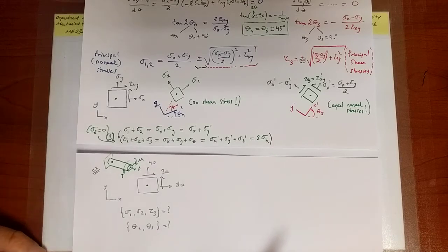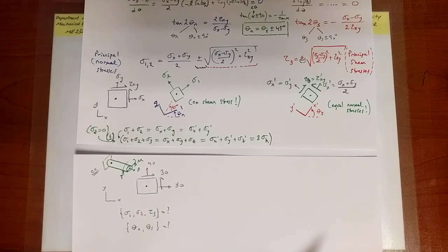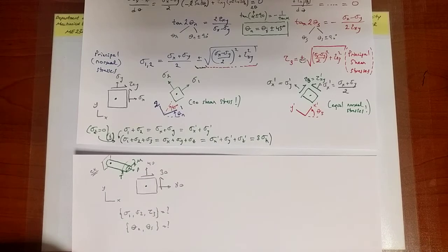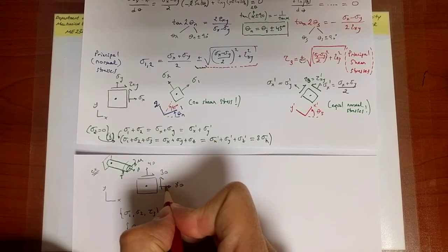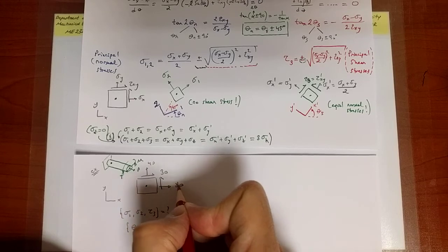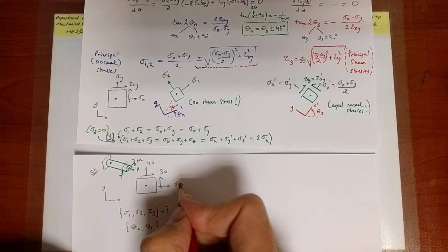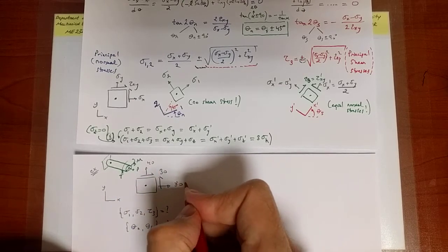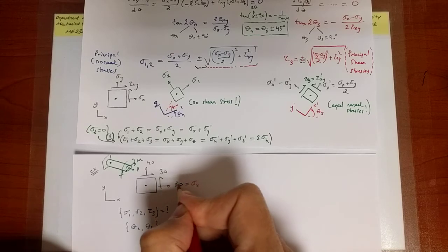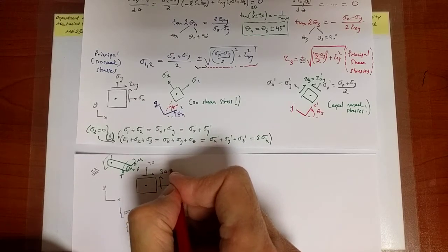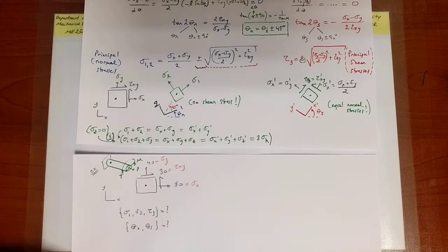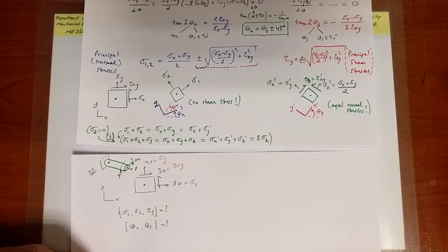And this I leave to you to a large extent. What you will find are two stresses. If you go ahead and plug these values in there, the only thing you have to be careful about is always the values. The arrows indicate the direction, or ultimately the sign, and the absolute values are given in terms of the magnitude here, right? So all the directions are the default directions. So here, this must be sigma x, and it is plus because it's in the default direction. This must be tau xy, already plus, and this must be sigma y. So all the stress components are positive in this case.